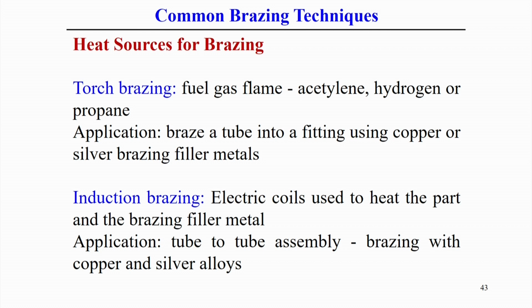So, what are the typical applications? When there is a tube that can be fitted into other components using copper or silver brazing filler metals, we can use an oxy-fuel torch as the source of heat. The heat can be easily controlled locally to a specified zone, simply by focusing the torch on that specific position.